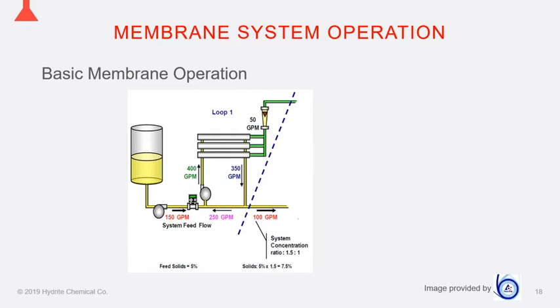What we've got now is the 350 coming down to the baseline. The pump needs 400. So coming down to the baseline, the flow will split. 250 will come and join the 150 to make my total of 400 coming out of that recirculation pump. We will then be left with 100 gallons a minute. That will feed our second loop.